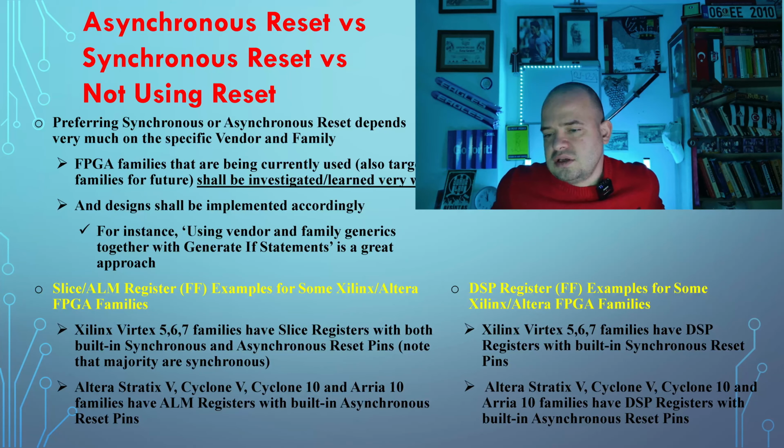Because Stratix 10 families, for instance, have DSP registers with built-in synchronous reset pins. Some newer architectures also have registers, flip-flops, without any resets. So yeah, you need to check family details, cross-check them.